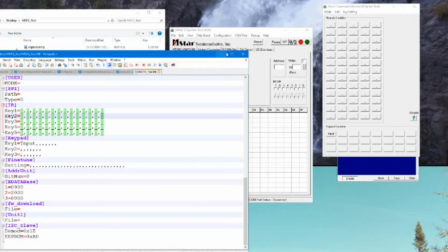Another feature of this chip, once you start futzing around with it, is you realize that there's a USB input option, and if you solder headers onto the unused USB pads on the circuit board and hook up something like a flash drive with MP4 files and bitmaps on it, you can actually use this as a built-in media player. It can play the files right off of a FAT32 formatted USB stick, which I thought was an interesting omission from the circuit board. Just by soldering on a header, they could easily have added some more features to this. So I personally really like these boards, as they're quite hackable.